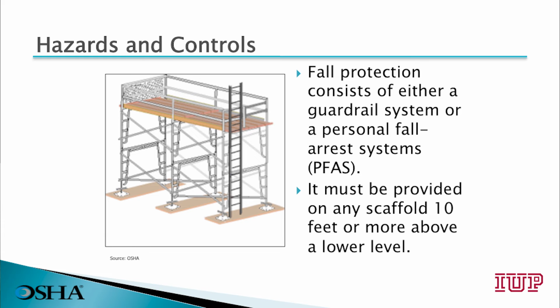When working on a scaffold, fall protection consists of either a guardrail system or a personal fall arrest system, and it must be provided on any scaffold 10 feet or higher when we have an unprotected edge.